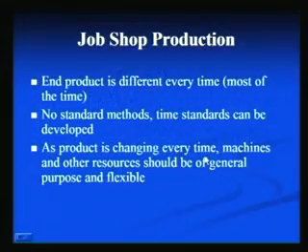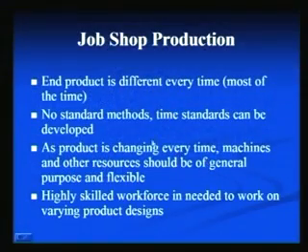Another characteristic of job shop type production system is that we need to employ a highly skilled workforce. The reason is very simple, because we are changing our product very frequently. Our product is changed every time. That is why there is a need to employ highly skilled workers who can work on different types of products, different types of situations, at times even at different places. In the case of the shipbuilding industry, because the product is very large in size, it cannot be manufactured in the plant. So, you have to move your workforce, your equipments, etc. to the product site itself. So, the workforce which you employ in this type of environment should be highly skilled.